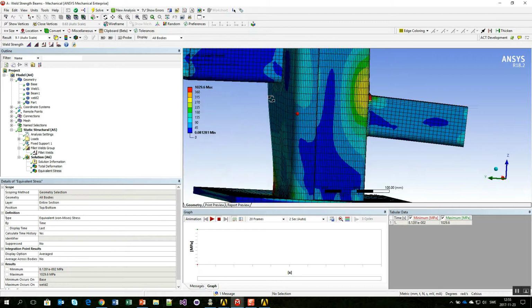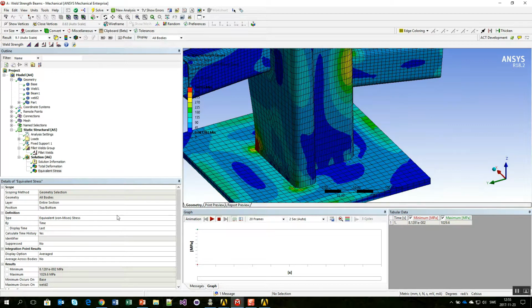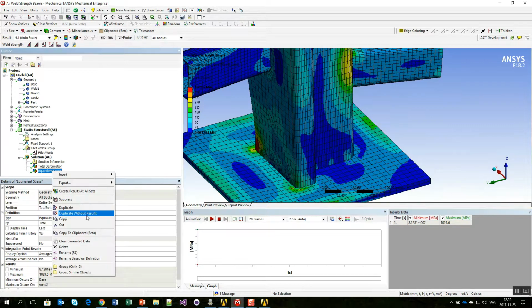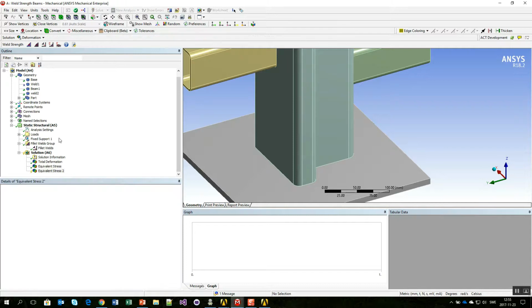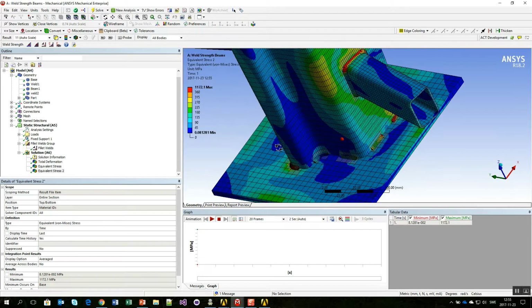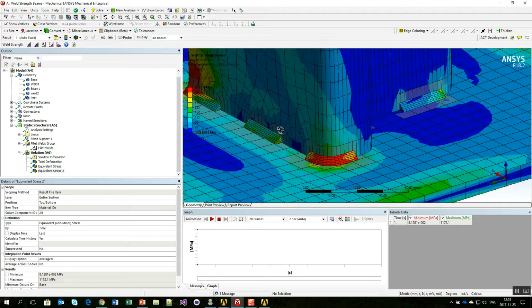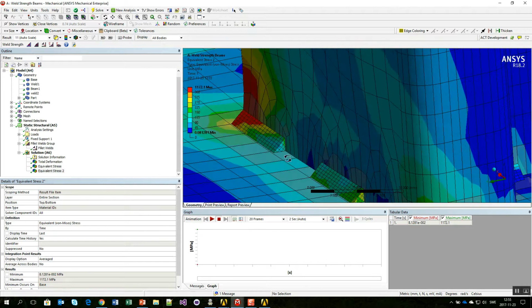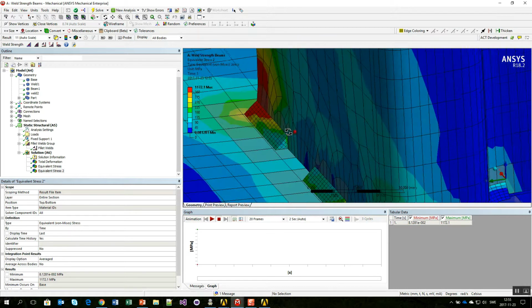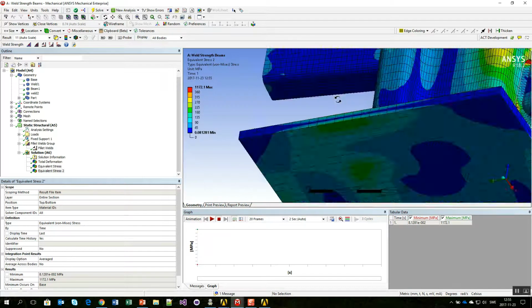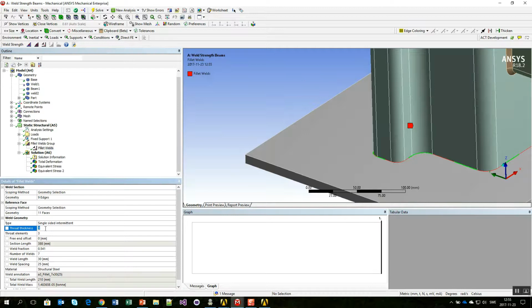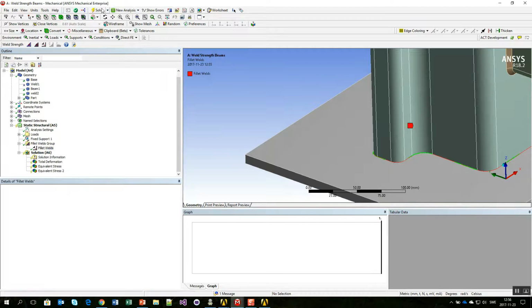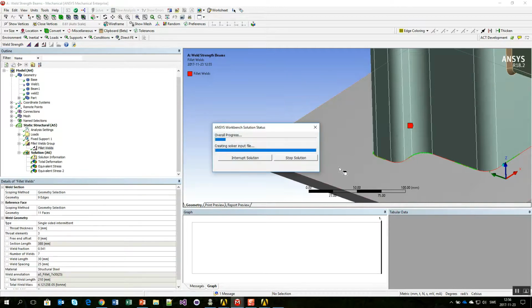Okay, so here I don't see the weld yet, and since it's not a geometry based weld, I need to use the results file item in order to see the weld. So here is our solid fillet welds with that specified sizing, and here I can now very easily test a different weld size, update the analysis.